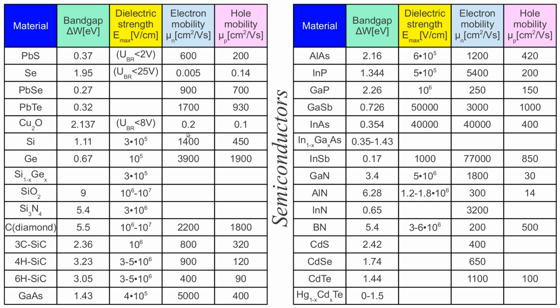But copper oxide today is a nuisance, because it grows on our antennas. Since it has rectification properties, fortunately it's not a very good rectifier, it causes distortion to our signals, and it causes intermodulation distortion, so it causes interference in radio communication. So copper oxide is a problem, but it's still a semiconductor.